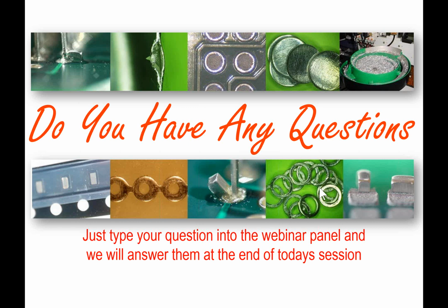I would totally agree, and let's for a moment forget about the metallurgy, let's forget about the reliability. If you've got to argue the case with a customer that no, we're not using exactly the same alloy, and then his customer's customer or the quality engineer, or if you've got some failures, then it's not a nice place to try and talk yourself out of. So if you possibly humanly can, use the same alloy. It just makes sense.